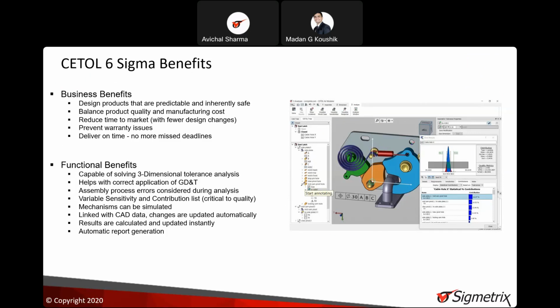So here you can see this particular feature, the mid cam pivot hole. This is a hole feature in the side plate. So this is the part and this is the hole feature. It has four variables, TX, TY, RX, RY: basically two translations which define the location of the hole, and two rotations, RX and RY, which define the orientation of the hole, the axis orientation.